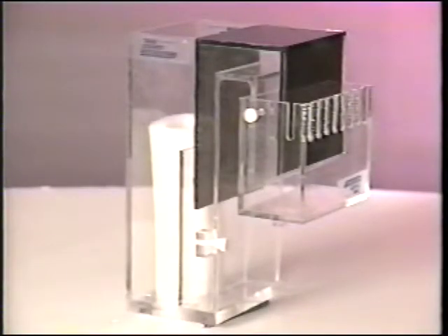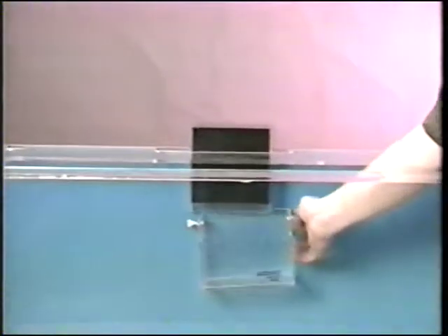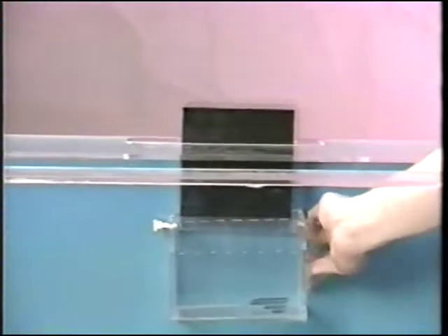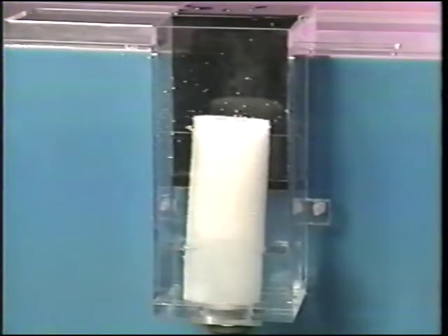Once the tank and stand are set up, the first item that needs to be installed is the pre-filter portion of the wet-dry filter. The pre-filter is installed by first placing the surface skimmer inside the aquarium. Once this is completed, the pre-filter core is placed directly behind the surface skimmer on the back side of the tank. Water flows between these two items by means of a siphon.